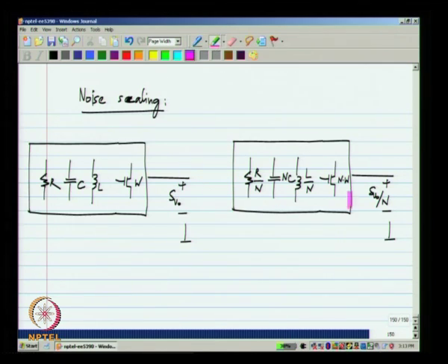So, this is a systematic way of scaling the noise of a circuit, and as I explained earlier, if I take these two circuits, the noiseless versions of them, and operate them with exactly the same inputs, the node voltages will be exactly the same in the two circuits. This is most easily imagined by starting off with the first circuit, and then you take an identical copy and operate them with the same inputs. Now, in the two copies, the corresponding node voltages will be exactly identical. You connect the corresponding nodes in parallel, what you will get will be a scaled circuit by a factor of 2. Now, because you are simply connecting nodes which are of the same potential, nothing else will change in the circuit, and the functionality of the circuit will remain exactly the same.